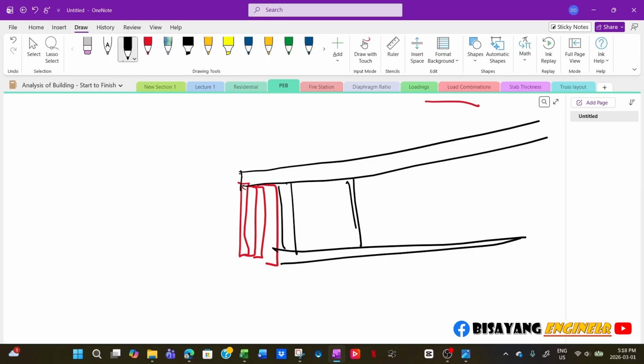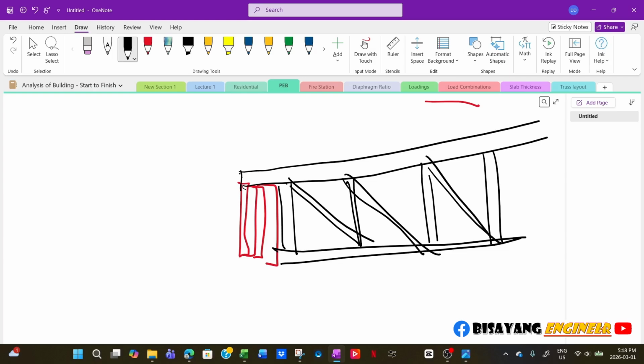So it's a top chord bearing, that one. And then the other in the other direction, because these are offset from each other, you will have full bearing, 7 inches bearing. Or if the bearing requirements only require two ply, that's 3.5. If 3.5 is fine, then you will butt the trusses at the mid location.